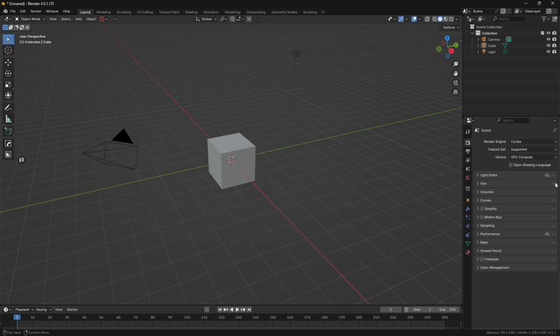Crucial warning. When you do this, Blender saves everything currently in your scene, including objects, render settings, and materials as the default. So, make sure your scene is empty or set up exactly how you want every new project to begin before you click Save. And just like that, you've taken control of the software instead of letting the software control you. Customizing your layout helps you stay in the creative flow longer.